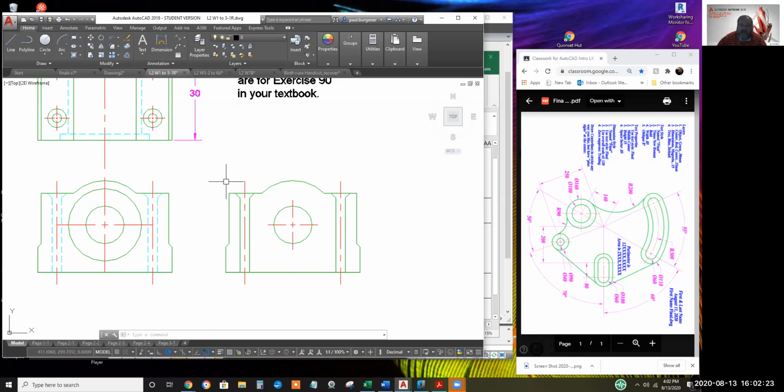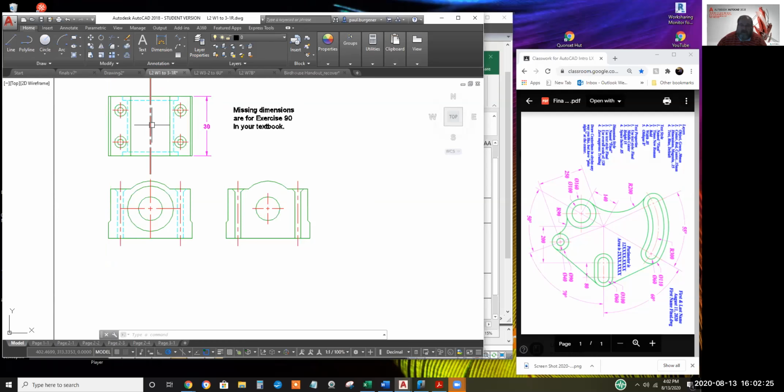A half section view is if you lop off a quarter of the object. So one side looks exactly like one of the orthographic views, and the other side is cut through, so you can have a half section and just simply cross hatch.